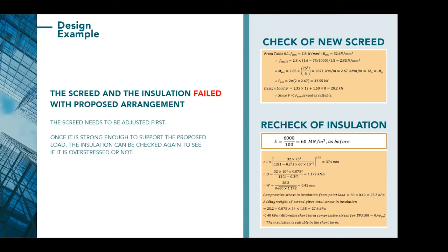So I suppose other things in the background could be, if we're using a semi-hydrate screed, they have very, very high tensile strengths, more so than standard concrete, but it depends on the manufacturer and the type of screed that's being used. So obviously we need to check all these things as well. You check with the manufacturer, they'll obviously have their information.